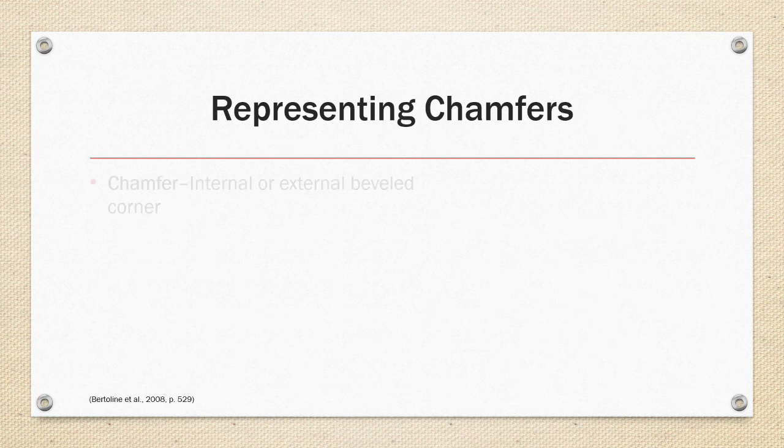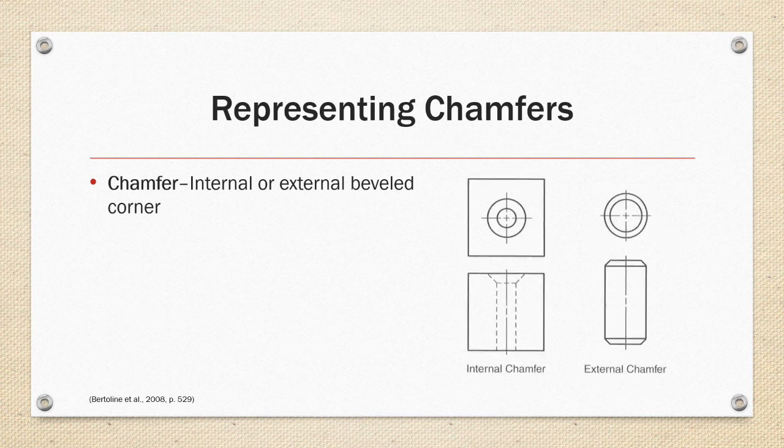Chamfers. Chamfers are similar to fillets and rounds, but are beveled corners that can occur as internal or external features. Chamfers are depicted on drawings as shown on the right and can be called out in a variety of ways that will be covered in a future lesson.